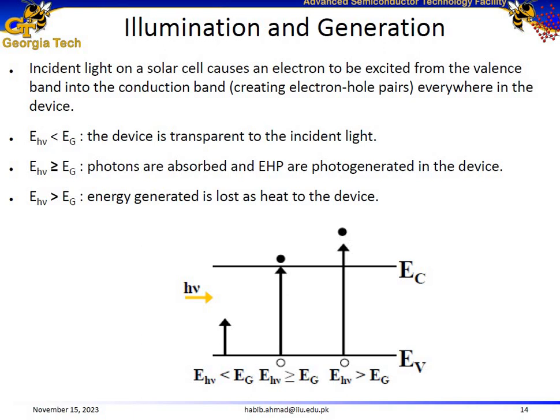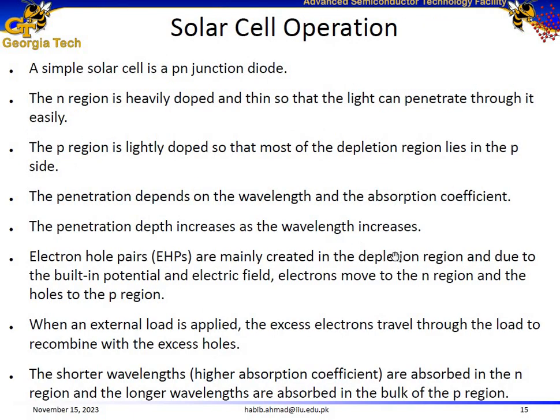And we know that electrons tend to settle down at the bottom of the conduction band. So with the passage of time, this electron would start moving towards the bottom of the conduction band in steps, because of Auger recombination. But in this process, it is going to lose some of its energy in the form of lattice vibrations or phonons, resulting in heating of the device.